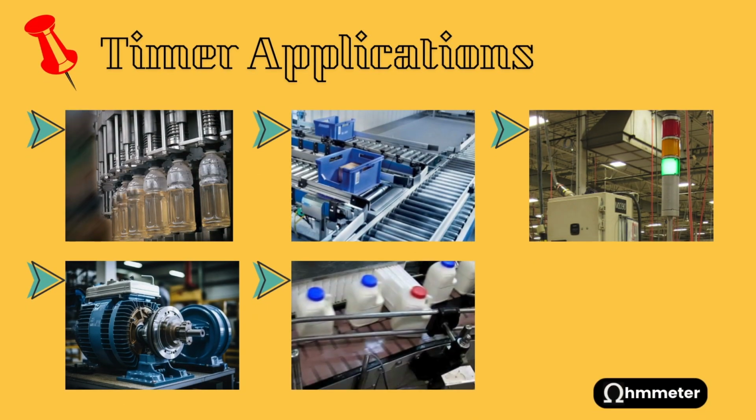In automation, timers are used to fill a bottle for a couple of seconds, delay a conveyor so another machine has time to finish, keep a motor running for a short time after input is removed, flash a lamp on and off, or pulse a reject solenoid for half a second. So it's important to know the different types of timers and how to program them inside the PLC.